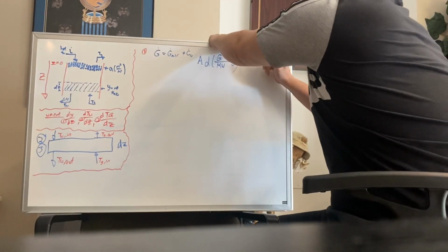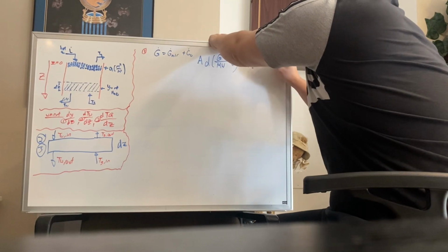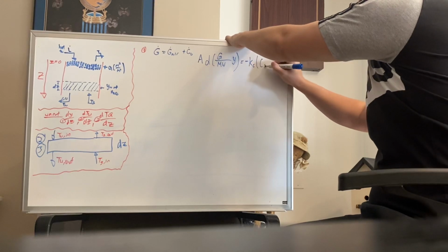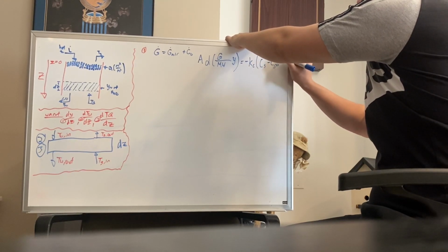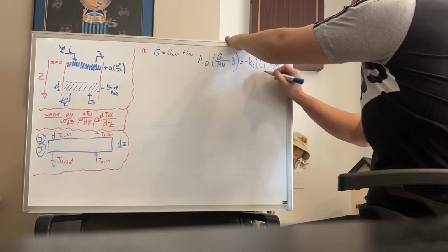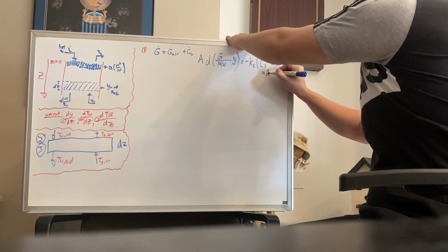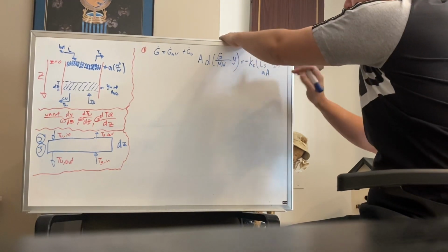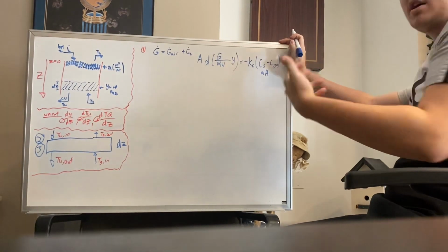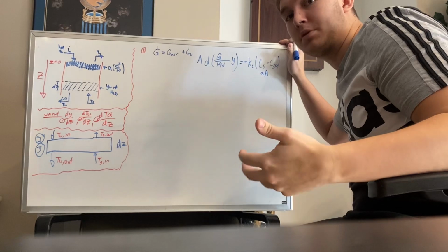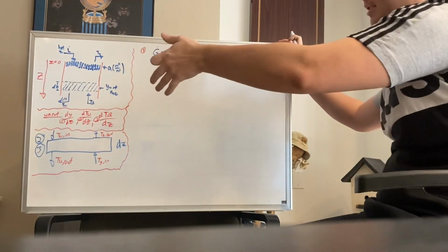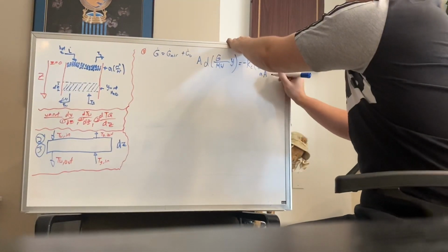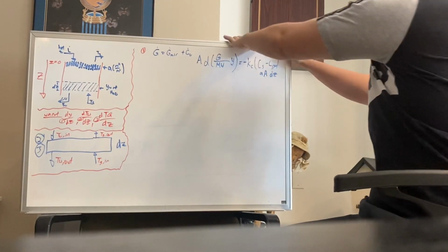So it's going to be negative Kc, the mass transfer coefficient, multiplied by the difference in the concentrations between the surface and some point far away, also multiplied by the cross-sectional area and the specific area, which is an area per volume basis. Whenever we see this small a times big A, it's an area per volume basis with respect to the volume of the cube compared to the area taken up by the packing pellets. And this is multiplied by dz.